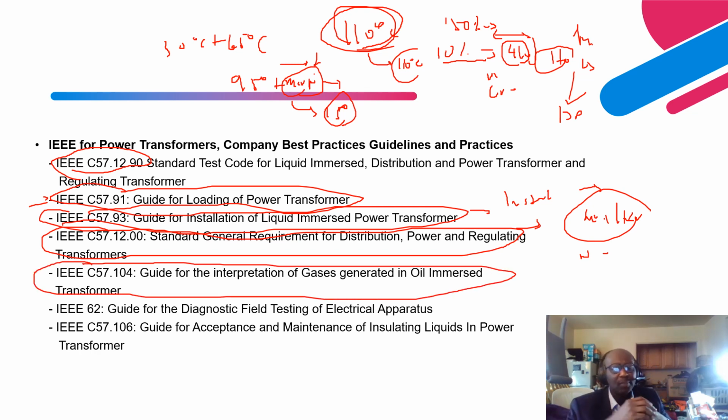Okay. Next standard is C57.104, right? Okay, so this is a guide that they use for interpretation of gases, right? Before, if let's say the gas exceeds the total combustible gas criteria, then basically you can move to the diagnosis stage. So what you can tell them is, okay, this standard is basically used to tabulate the gas concentration after you perform a DGA, right? Okay, so it's been grouped into 4 conditions: condition 1, condition 2, condition 3, condition 4, right?